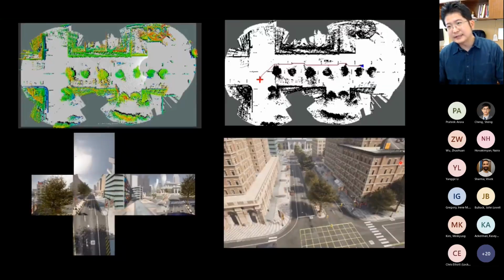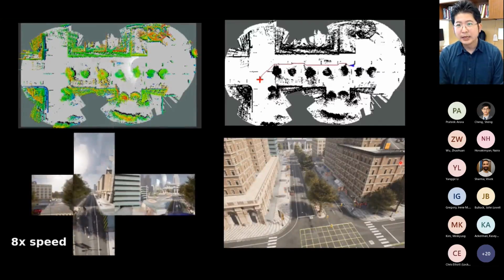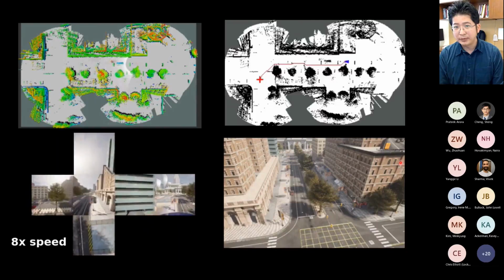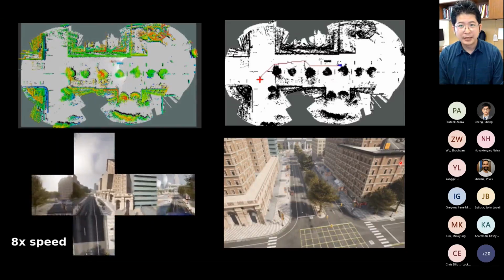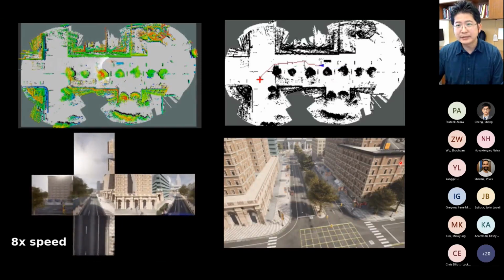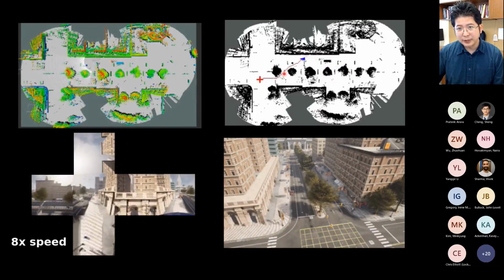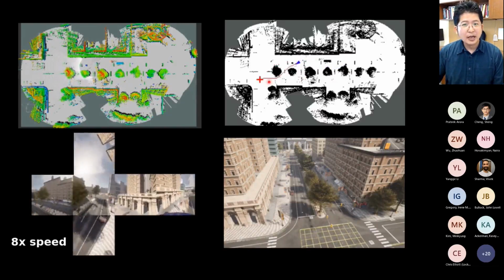And then using this, I made my first pass at real-time path planning using A*, very basic, but the popular one. And then we also use Octomap to get the occupancy grid. At this point, it's just 2D path planning. You can actually see that the path is calculated in real time. As you can see, the path is changing.